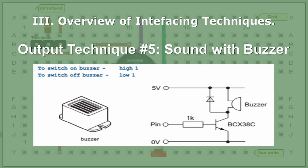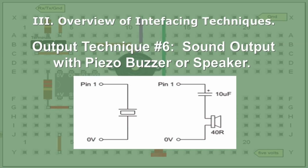Notice the circuit's almost the same. It's got the same dropping resistor there across the base to pin 1. You run pin 1 to high, the current goes to the transistor, and the buzzer goes like that, for example. Number 6, piezo buzzer. Very simple technique. You can see the circuit there is very simple.